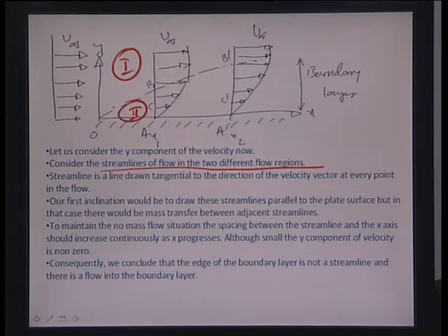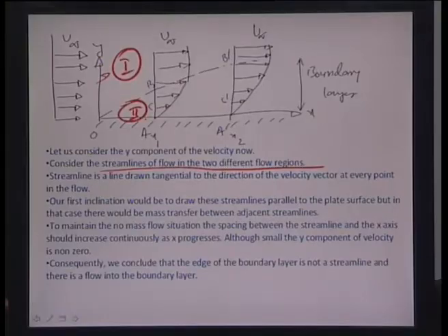Interestingly, if there are parallel streamlines generated parallel to the surface of the plates, and we are saying that in one case there is a lesser amount of velocity which increases all the way to u infinity, in another case there is all u infinity, there will not be much problem in region 1 or the inviscid region, but in region 2 definitely there is going to be mass transfer in the y direction, right, because of principally the amount of feed of a fluid.